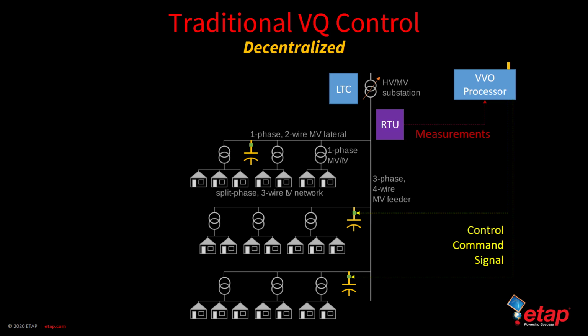Another drawback to this approach is that as the system changes significantly or is operated in abnormal configurations for long periods, the logic on which the substation IED will be making decisions will be based on a stale network model configuration. In some instances, control center operators might turn off the centralized VVC at the substation because many power quality issues may be generated when this VVC method is working within an old or stale network model.